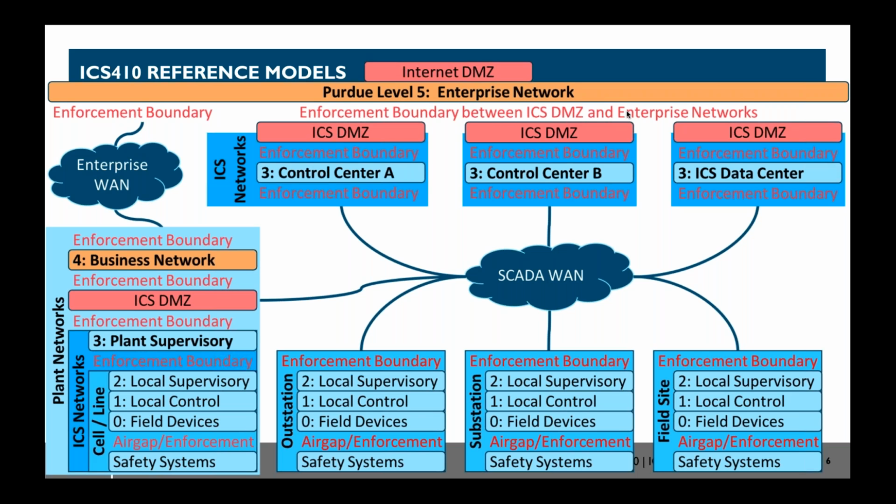When we try to map something like this larger, more complex SCADA network to the PURDUE model, right, we have to kind of be careful. Sometimes there's some confusion there. And many companies will map this differently. So don't be surprised if a company that already is using the PURDUE model with a large SCADA infrastructure has labeled things a little differently or has assigned their PURDUE levels a little differently. Part of the problem is there's never been good solid guidance consistent across the board, which is one thing we're trying to rectify here in the ICS 410 class, is to try to standardize on a model here.